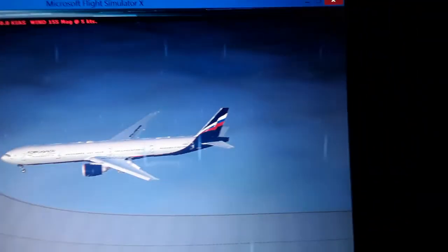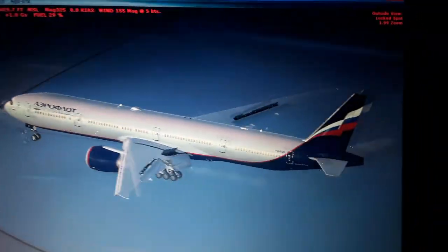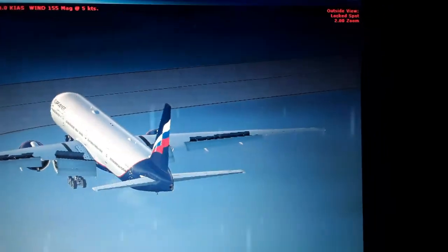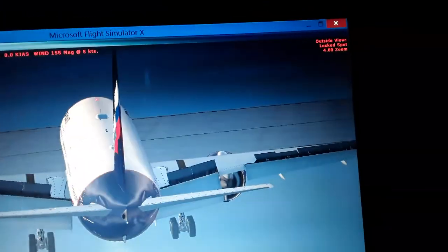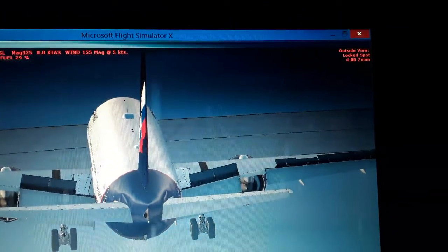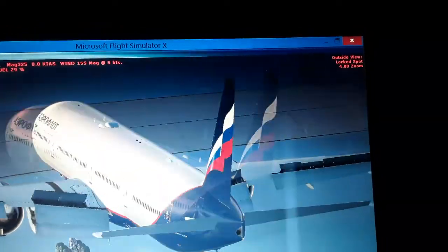So this creates the aerodynamic lift, and after that we have this center of gravity and center of aerodynamic pressure. We transfer all the moment arms for directional control using the side stick here, as I said, using the elevator pitch up and pitch down that is located at a distance away from the center of aerodynamic lift and the center of gravity of the aircraft, where the weight is located. That makes the aircraft pitch up like this, using the horizontal tail to create a moment arm around its axis.